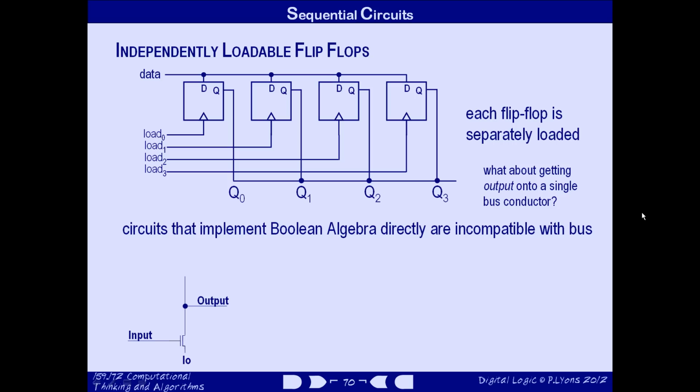However, it's only half the circuit. It has a way to ensure that the output is low when the input is high, but it doesn't yet have any way of making the output high when the input is low. To do that, we connect up a second transistor to the input and to a high voltage. Now, you can see that this transistor is a little different from the first. The little circle that you can see indicates that it becomes an electrical conductor when its input voltage is low. Otherwise, the top and bottom of the transistor aren't electrically connected.